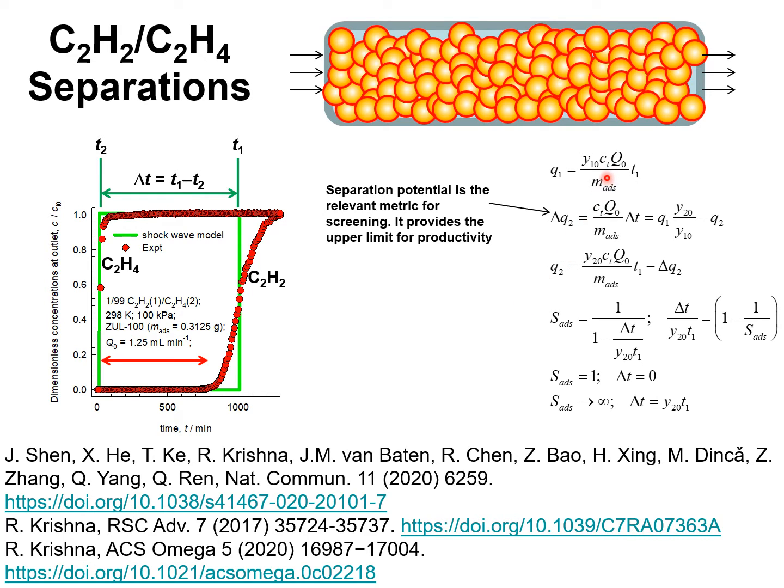This, in the Shockwave model for a fixed bed adsorber, is given by this expression, where Y10 is the mole fraction of component 1 at the inlet, Ct is the total molar concentration of the mixture at the pressure of 100 kilopascal and temperature of 298 Kelvin.